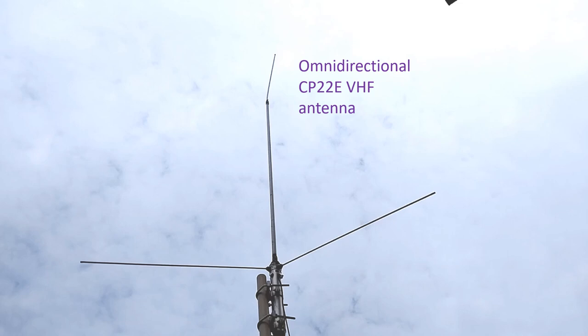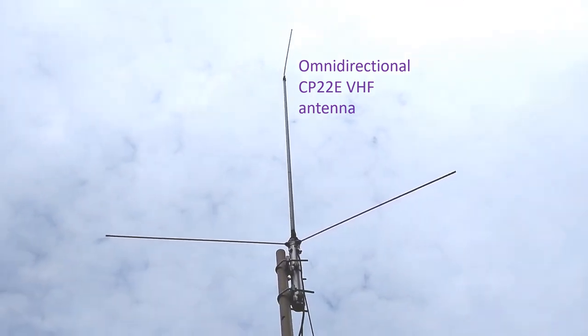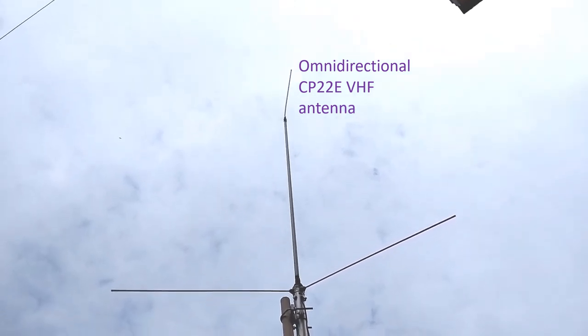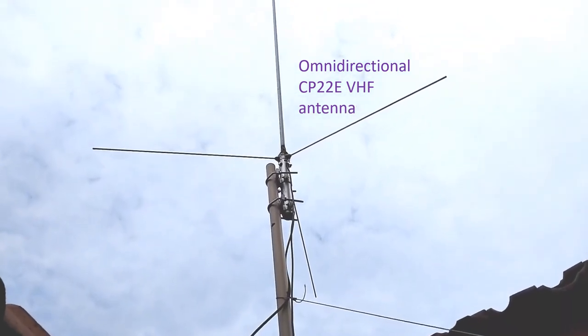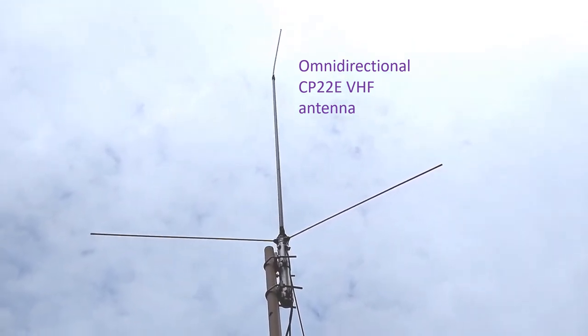In both instances, we will go for an omnidirectional antenna. Omnidirectional antenna gain can be increased by having more vertically stacked elements with appropriate phasing coils in between. This is my CP22E antenna. You can see a phasing coil between the two elements. You can see that the upper element is a bit bent by wear and tear, and this has been mounted on a CPVC pipe, 3 meters of CPVC pipe, again on my first floor terrace.